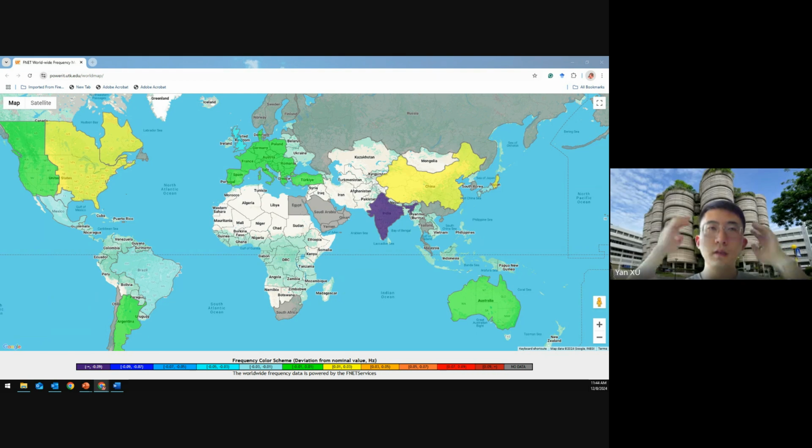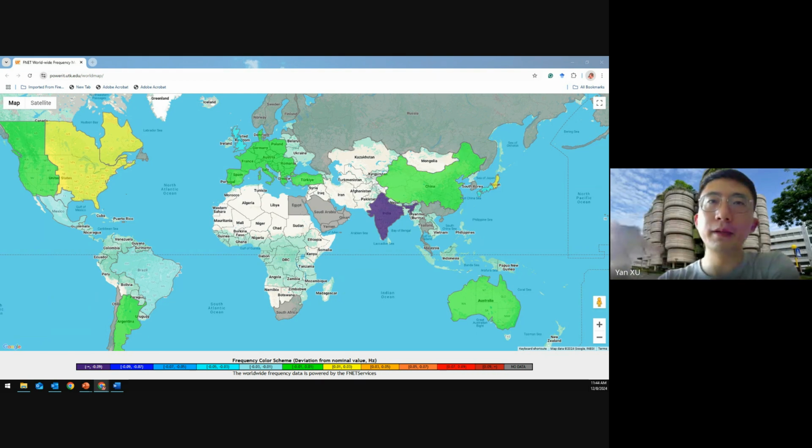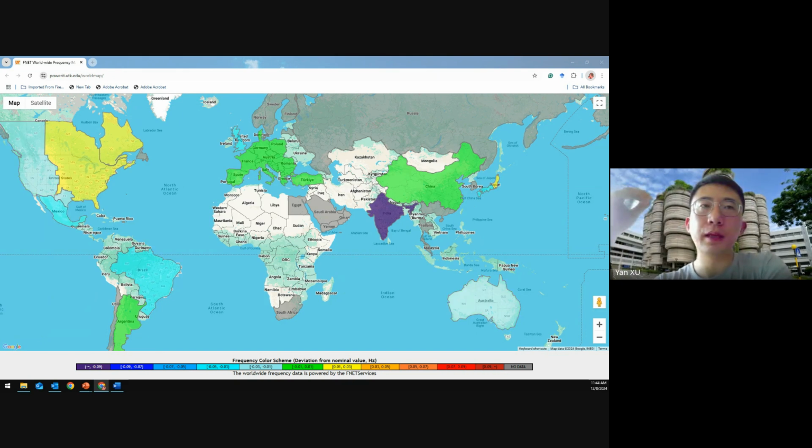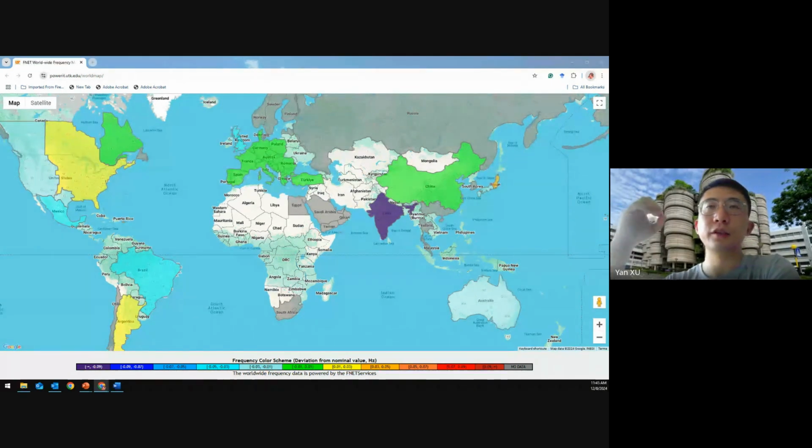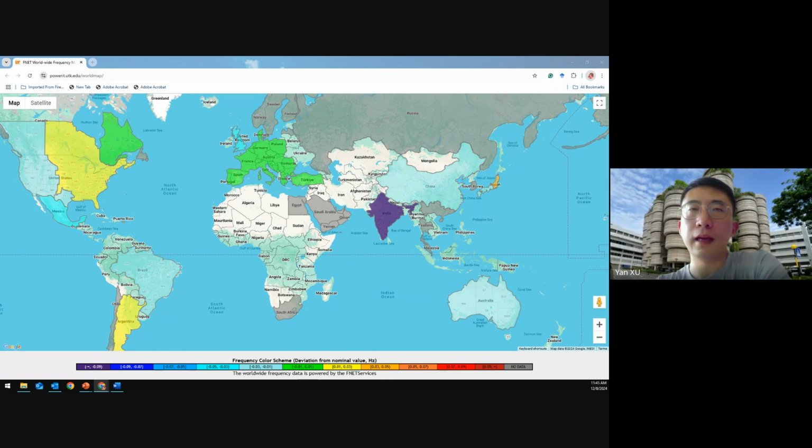In our research group, we have designed this compensation-based control system, which takes into consideration the time delay. During the control design stage, we add a compensation unit. This unit can cope with the time delay. Because from a dynamic perspective, the time delay will lead to instability. If the time delay is beyond a certain limit, the system will become unstable. So it's very important to consider time delay.